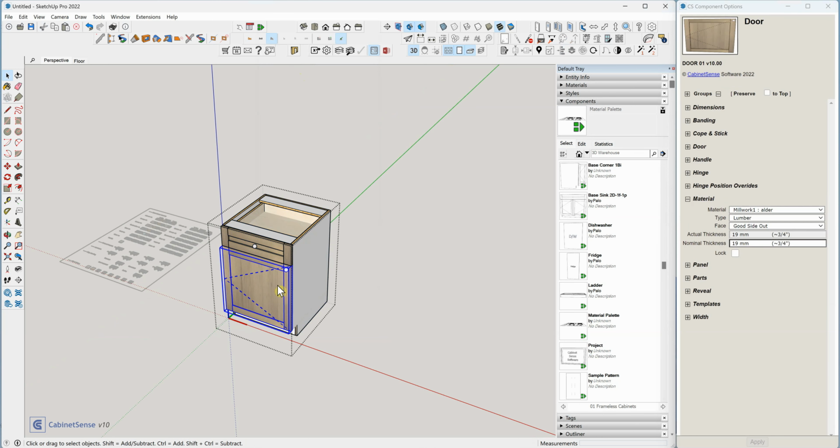So in this case, let's say that we've got a room of cabinets and we don't know where this 16 millimeter material is being used. We know that's not right. We can go to the job review material screen, and now it lists by material, by thicknesses. It also lists by part. And again, we can sort by any column. Here's our 16 millimeter material. All we have to do is click on the magnifying glass to go find where that's being referenced.